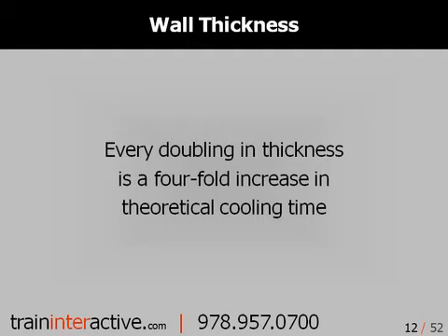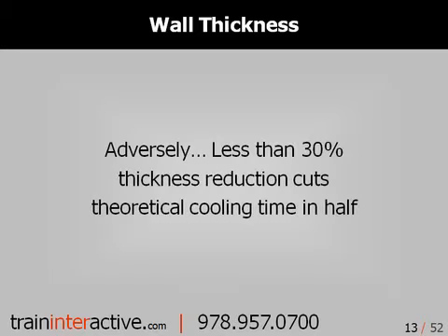This effect becomes even more obvious in semi-crystalline materials such as nylon and polypropylene that shrink as much as 5%. Conversely, less than a 30% reduction in thickness will cut theoretical cooling time in half. In practice, the actual cooling time will decrease even more due to the improved heat transfer.